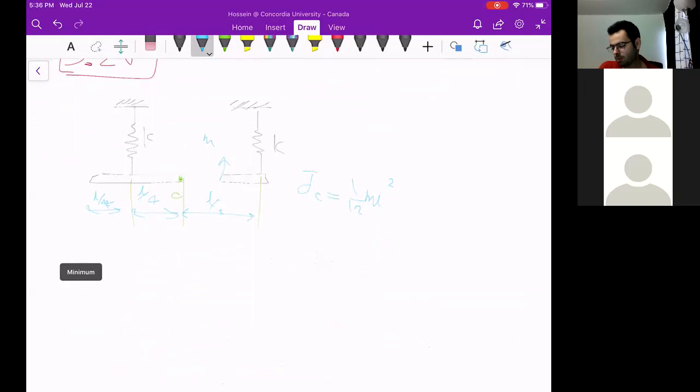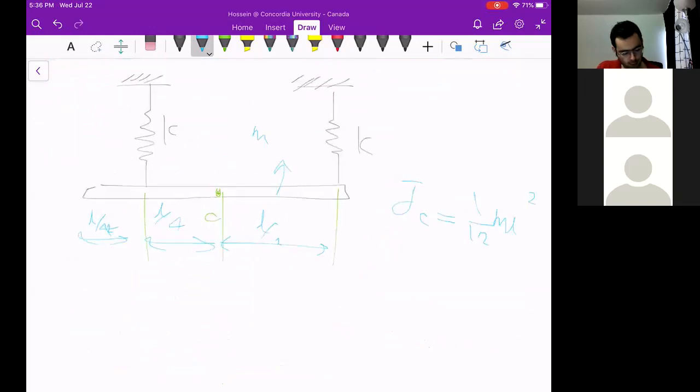So how could we determine natural frequency and mode shape? We have to derive the equation of motion. As soon as you attach this uniform bar to the spring, there is a static equilibrium position, a static deflection, and then this uniform bar can independently move upward and downward, and at the same time independently rotate.